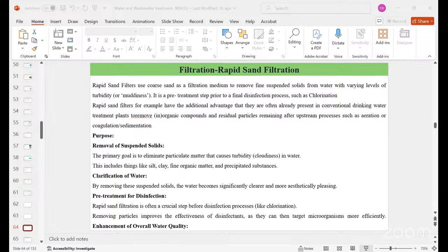Vacuum filtration is where a vacuum is used to create a pressure difference, pulling the fluid down through the filter. Another one is membrane filtration, which uses thin membranes, ultra membranes, nano membranes. All of these are used with a precise pore size, very minute in size, 0.2, 0.1, not 1 micron in size. So these kinds of sizes will be used for separation of the solids and all.